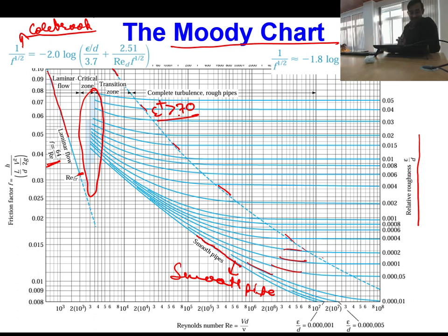Okay, and this Colebrook's correlation can mimic the complete Moody diagram within an accuracy of 10 to 15%. But then one more modified correlation is proposed which can mimic the Moody's diagram with less than 5% error, and this is the second correlation.